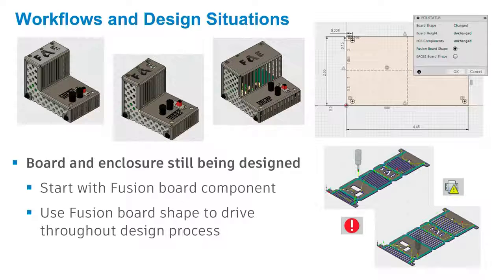We moved all the knobs and the switch around, all of that. This example, actually, when we were working with this, those knobs moved all over that board, to be honest with you. The knobs, the on-off switch, as well as the LED display. So we were constantly going back and forth because we had to take into consideration the thermal from the heat sink was going to damage our LED, so all sorts of changes were needing to be done on the circuit board and then pushing back and forth. And when we use the Fusion board shape, we can see down in the corner.